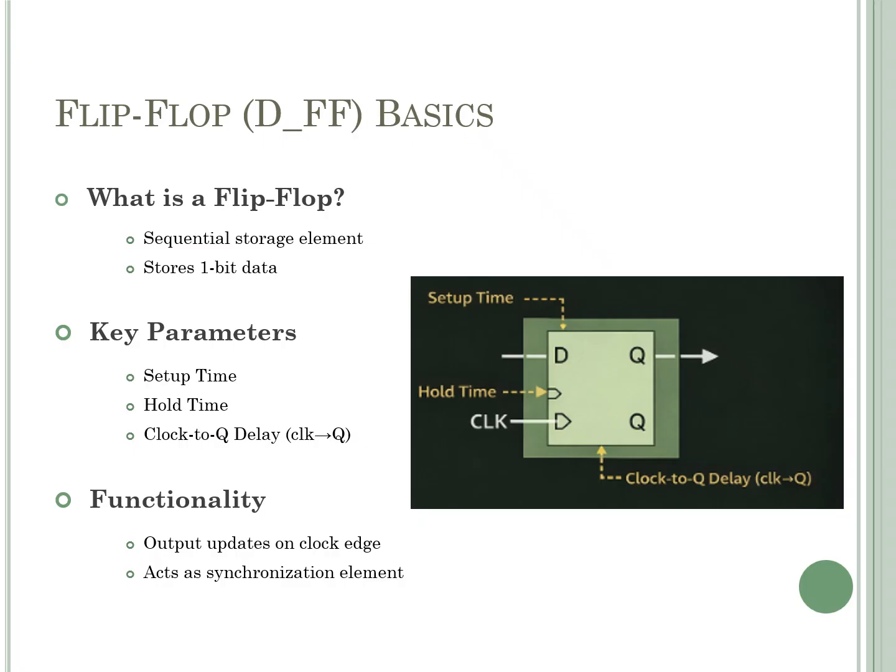This is why the flip-flop is important. Also, a flip-flop acts as a synchronization element in a digital circuit. They control when data moves. They ensure everything happens in sync with the clock. In a timing path, the launch flip-flop sends the data and the capture flip-flop receives the data.